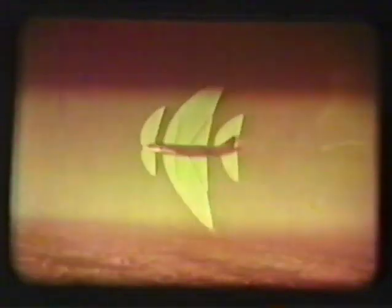So when considering airflow, it's convenient to divide flying speeds into three ranges. The subsonic speed range, covering all speeds at which the flow everywhere around the aircraft is subsonic. The transonic range, covering all speeds at which the airflow is mixed, part subsonic, part supersonic. That is, from M crit to about Mach 1.3. And the supersonic range, covering speeds at which the main flow everywhere is supersonic.